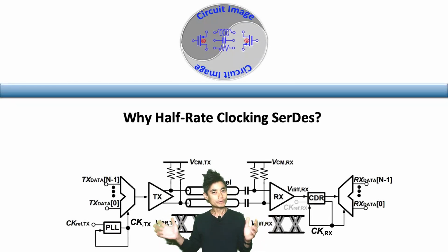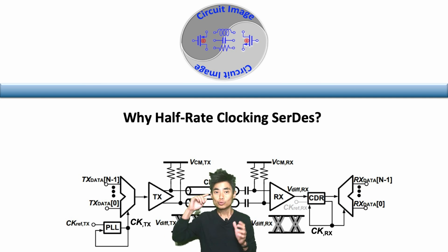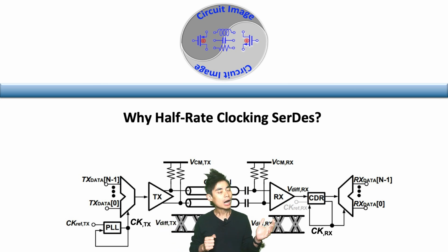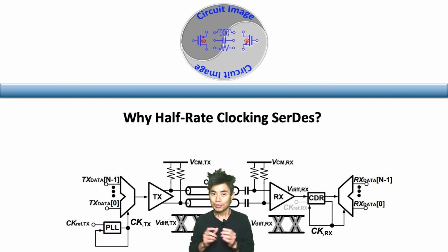Hello, we will talk about the high level or big picture signaling in terms of the data rate in a SerDes architecture. But we never talk about the high level design considerations in terms of the clock rate in a SerDes architecture. Therefore, people may think that we should generate or recover the data at the TX and RX respectively through the clock rate same as the data rate, which is called full rate clock SerDes.